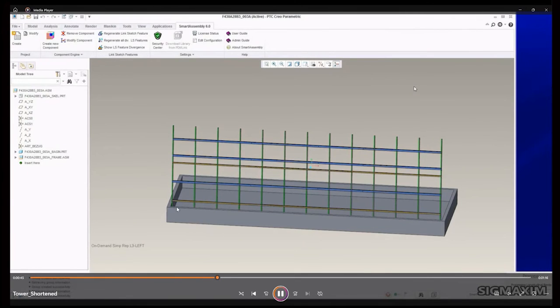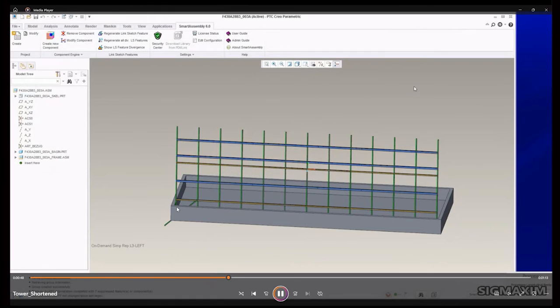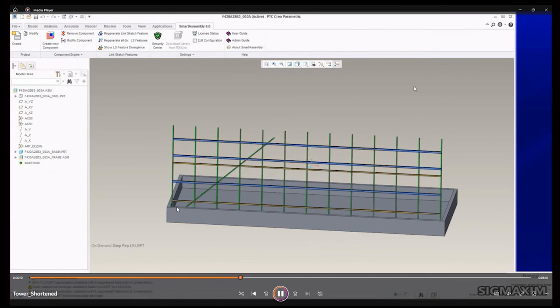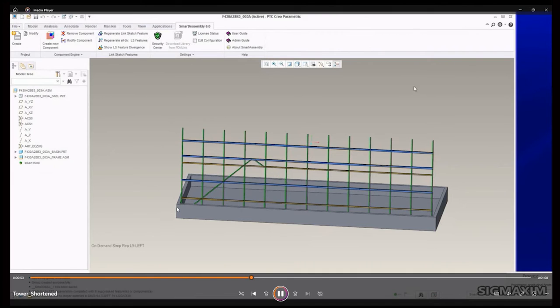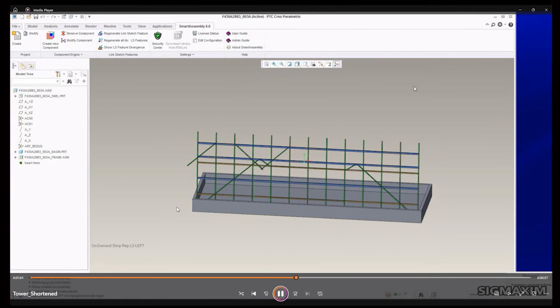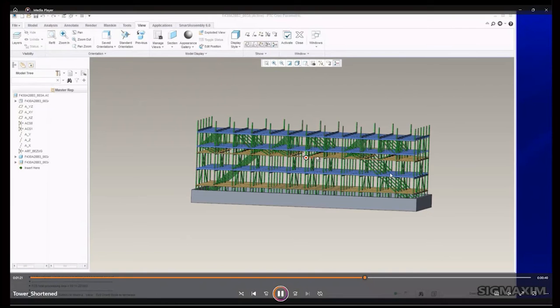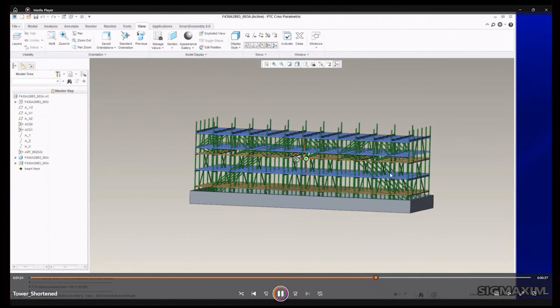Now, this being such a large assembly, we cannot build everything with the geometry in the same session. So we're handling that session with on-the-fly simplified reps. We build these on-the-fly simplified reps to make sure things can be loaded in memory as we build this configuration and it continues to build. As it continues, we figure out what we need to load in order to calculate the rest and build it.